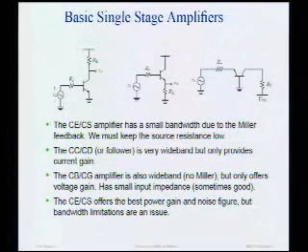Now, all these amplifiers are good and well, but usually we don't use them, and that's because each one has a weakness. Let's start out with the common source amplifier. The strength of the common source amplifier, common emitter amplifier, is gain. It has lots of power gain. In this course, you're going to get into the habit of thinking about power gain. I know up to now you've thought more about voltage gain or current gain. In this class, power is money. Power gain means you have to have current gain and voltage gain, right? So the common source amplifier is good because it has both.